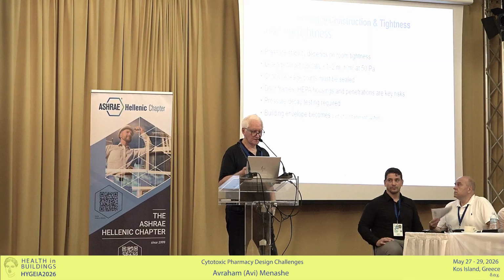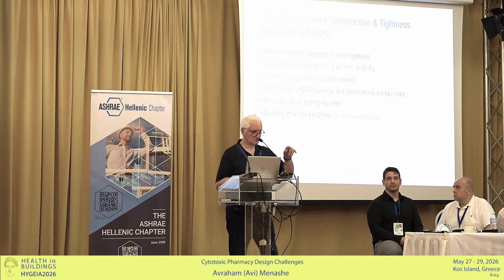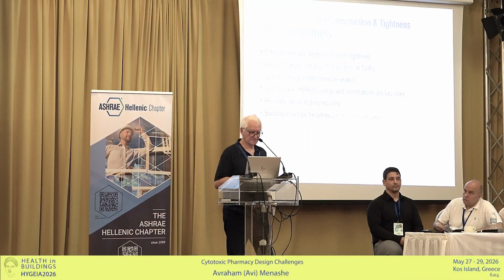Door frames, HEPA housings and penetrations are key risks. Sometimes we have gases coming from outside into the laboratory, into the pharmacy, so all the penetrations must be 100% sealed. Always when I come for commissioning, I have a big fight with the contractor, and I show him, listen, here you have to seal, here you have to seal, because it sometimes takes 3-4 times until you come to the final results.